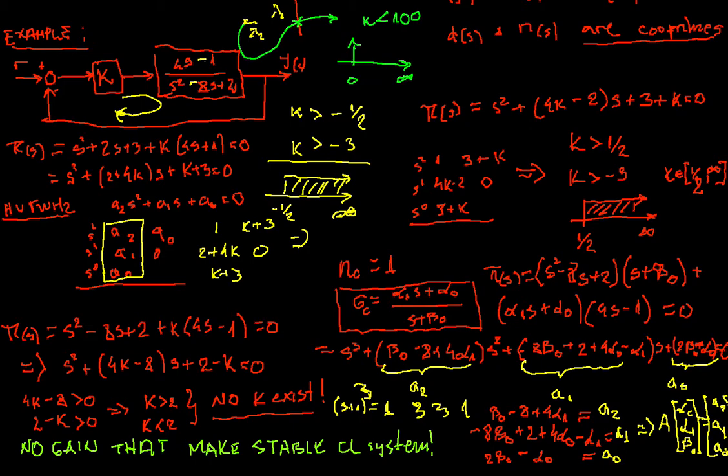Okay, in this way we're just solving the system of linear equations, and this system is trivially solvable for us. In other words, in the case when we could not stabilize with a gain, we had to increase the order of the controller to provide the new set of parameters given here, such that we can guarantee the closed loop system stability. In general, this is the procedure that we always follow when we design the controller.